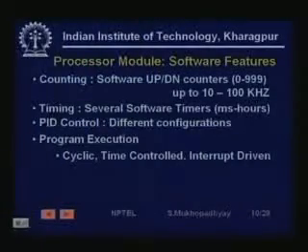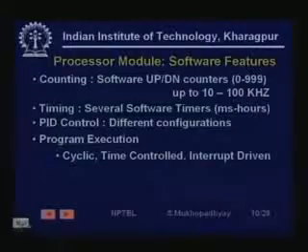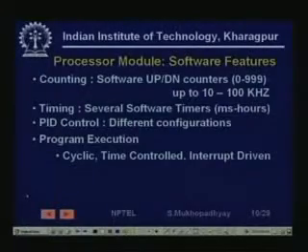The program execution in these systems is very interesting. There are generally 3-4 different types of program execution modes specified. For example, a mode could be cyclic. By cyclic we mean that you have a number of computational tasks, just like RLL program execution. So, begin here, come to the end, start all over again. So, this just goes on. Typically cycle time remains more or less constant, but it could vary a little bit depending on the program logic.